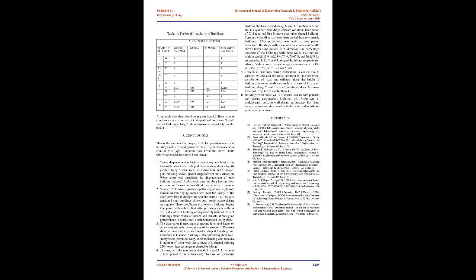3. The base shear is maximum at ground level and keeps on decreasing towards the top storey of the structure. The storey shear is maximum in rectangular-shaped building and minimum in L-shaped buildings. After providing shear walls, storey shear increased. Storey shear increases with increase in number of shear walls. Storey shear of L-shaped building is 22% lower than rectangular-shaped buildings.